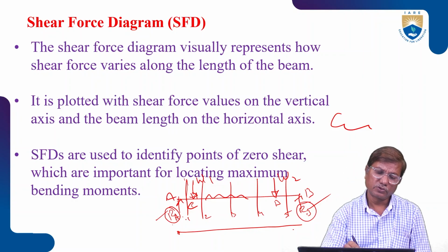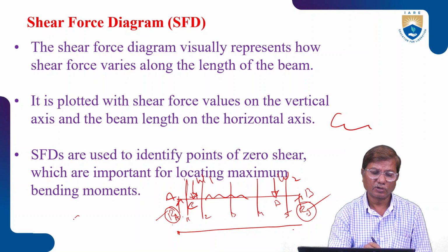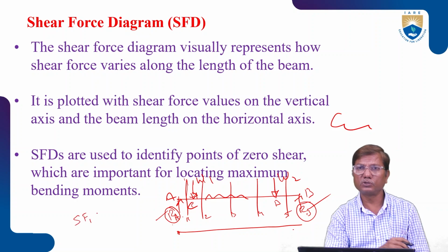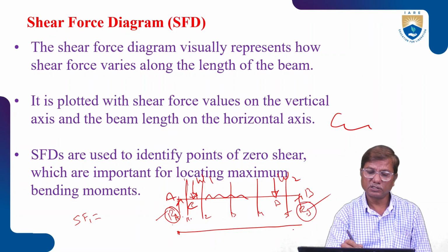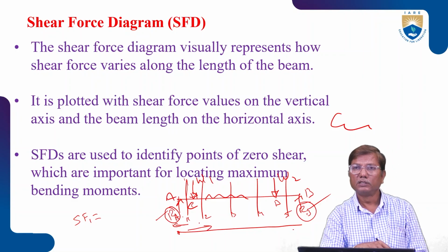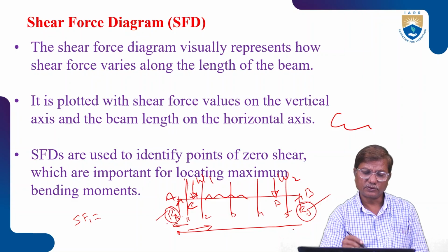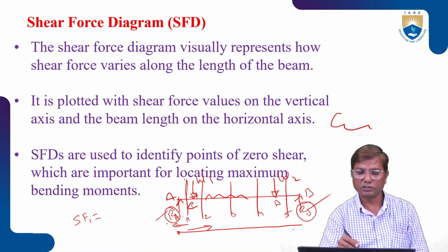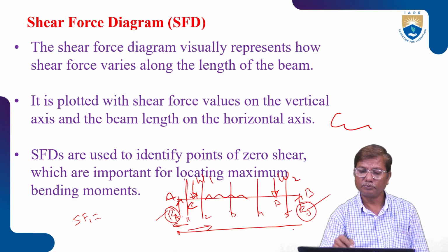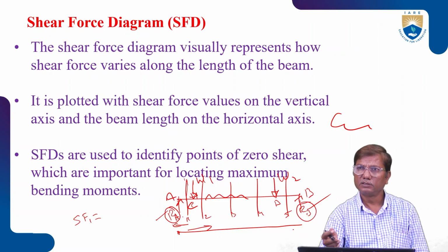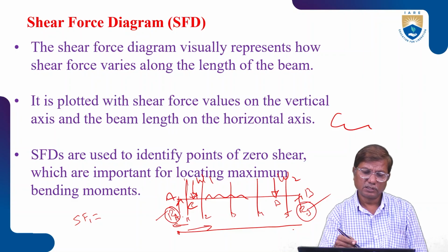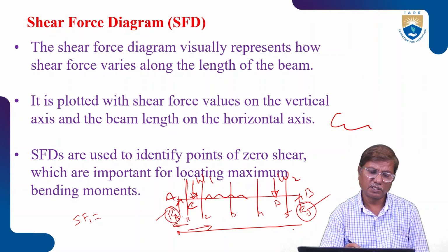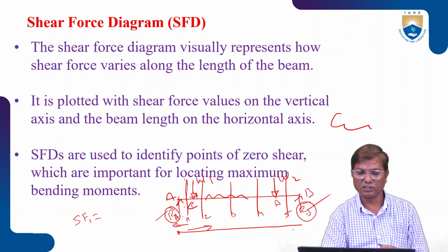Now the shear force at this section. To calculate shear force at section 1, we have to consider either the left side of that section or the right side, any one. Generally we consider the left side here because there are fewer forces to the left compared to the right side. It is just the summation of forces either to the left or to the right. We consider the left side here because there is only one force, that is the reaction RA.